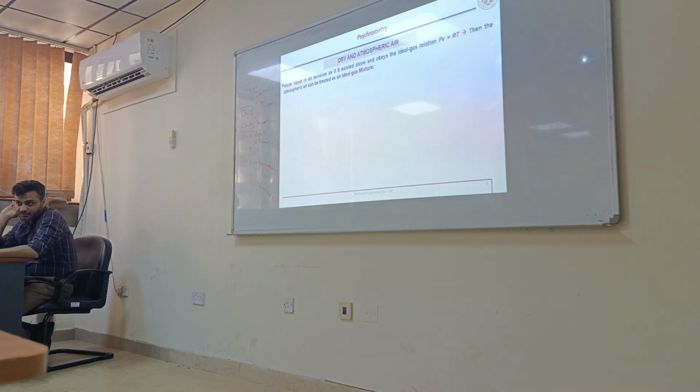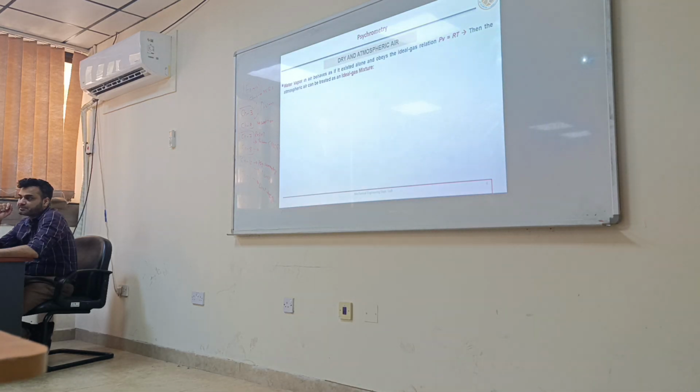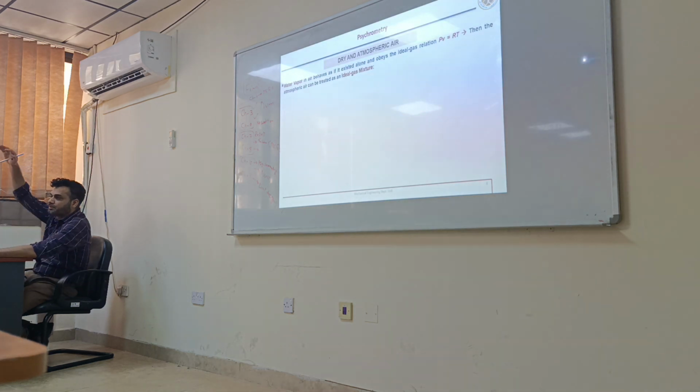We have discussed it in thermo too, but I think the majority have forgotten. Generally speaking, you cannot treat water vapor as an ideal gas, but we can treat a gas as ideal if its pressure is very low, at very low pressures or at very high temperatures.